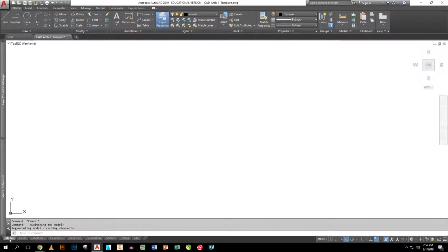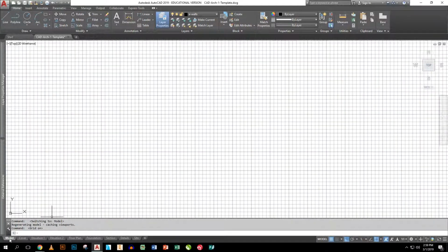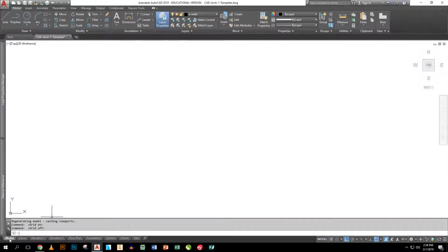Normally that defaults to black. Sometimes it has a grid on it, like this. That's one of our function keys. I can turn it on and off. I actually don't draw with the grid. I turn mine off immediately. I also turn off my snap. I do turn on my O snaps. I do use my ortholock, and I use my polar snaps as well. So as I'm looking at this, these are the things I'm doing now.